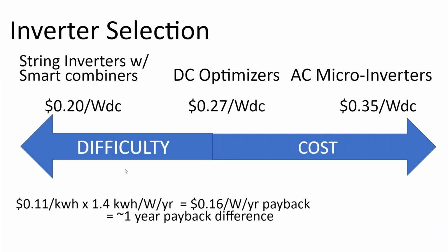So it might be that you can still use a string inverter and find some third-party boxes to put in line rather than an integrated system, and maybe that'll save you some money or maybe it won't. Generally speaking, when I'm doing string inverters now, they're not on the rooftop, they're down on the ground, at which point they're a great option. If you have an unshaded solar ground mount, string inverters absolutely are the way to go because they're just as good, if not better, and cheaper.